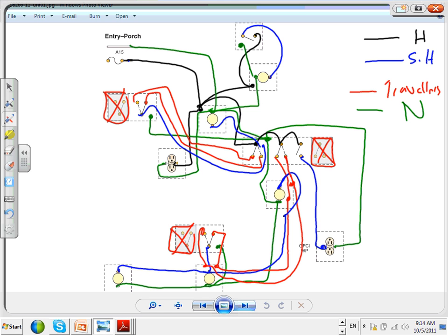So be very careful, guys. When you have two switches in the same box coming from two different circuits, pull the code right now. The box has a neutral in it, but this neutral is really not that circuit's neutral. So make sure you bring a circuit neutral when you come here. I would probably bring the neutral from the circuit that feeds that switch.